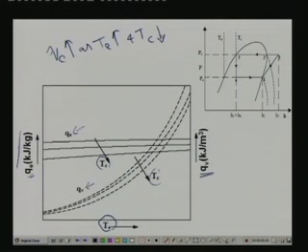That you can easily find out from this pH diagram. As I have already discussed in the last class, this is your refrigeration effect or this is your QE. If you keep the condenser temperature constant and vary the evaporator temperature, for example increasing the evaporator temperature, that means this line shifts up, and you have the new cycle like this. The increase in refrigeration effect is very small, only this much. This purely depends upon the slope of the saturated vapor curve on the pH diagram, and you can see that it is almost vertical. So, the change in QE with TE is marginal.